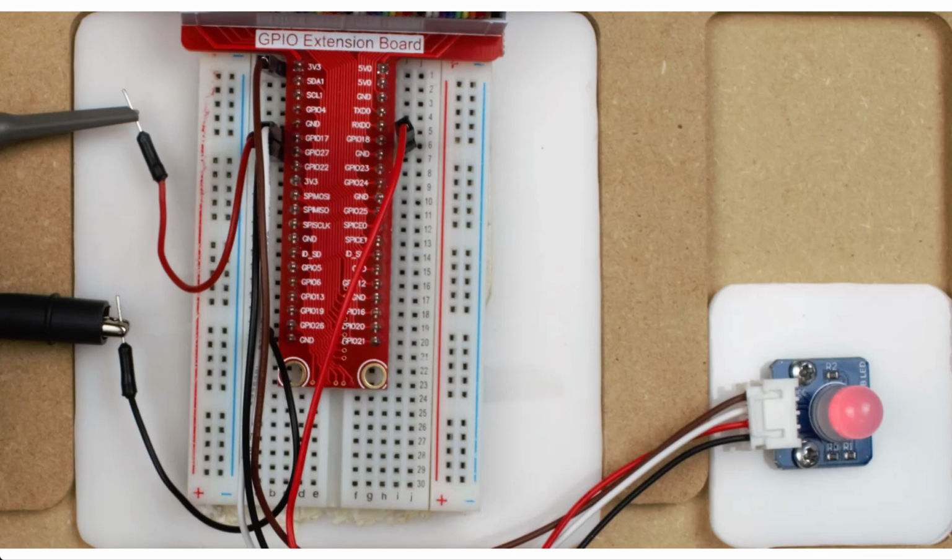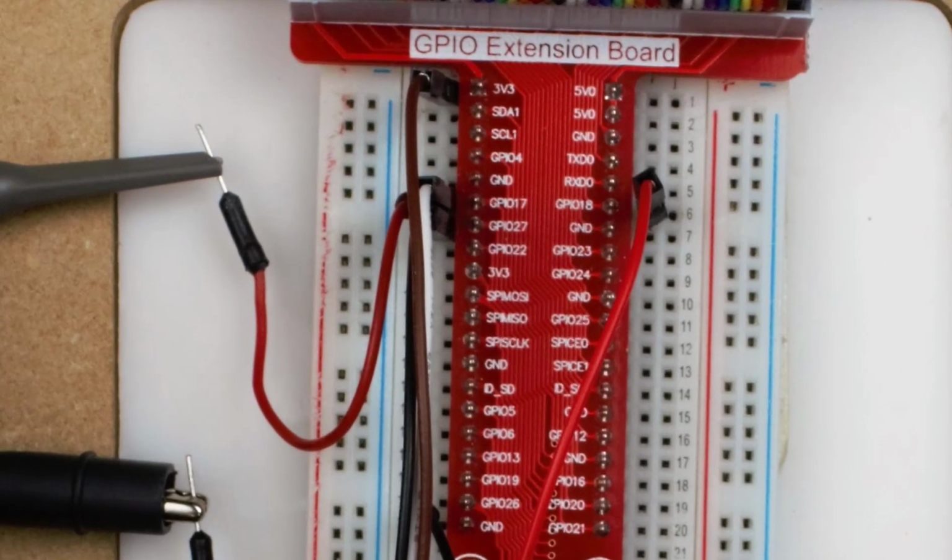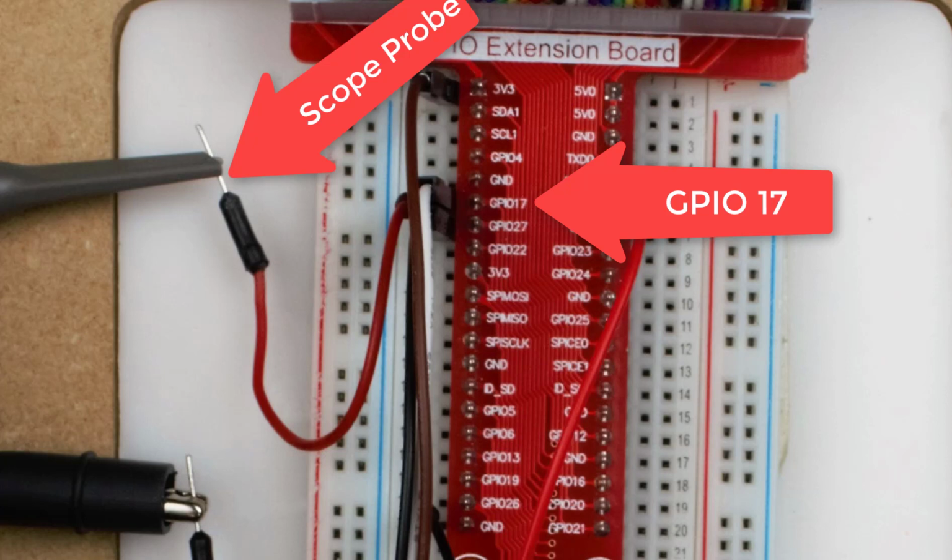Now we will set up the oscilloscope in order to measure the digital signal that we are sending out from the Raspberry Pi. In order to set up the oscilloscope, we will put a jumper wire on pin GPIO 17. Just put it in the same line as the white wire that we already have there.